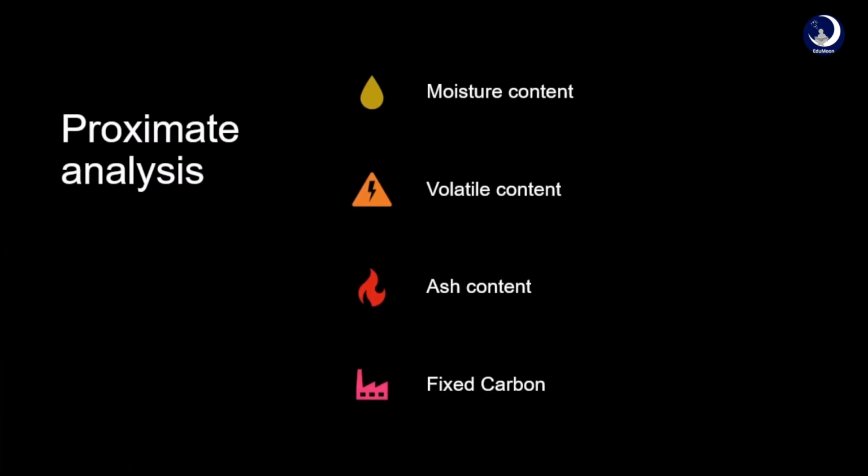Coming to proximate analysis, it deals with moisture content, volatile content, ash content and fixed carbon content. Proximate analysis, which includes the determination of these, will give us quick valuable information regarding the commercial classification and determination of suitability for particular industrial use.